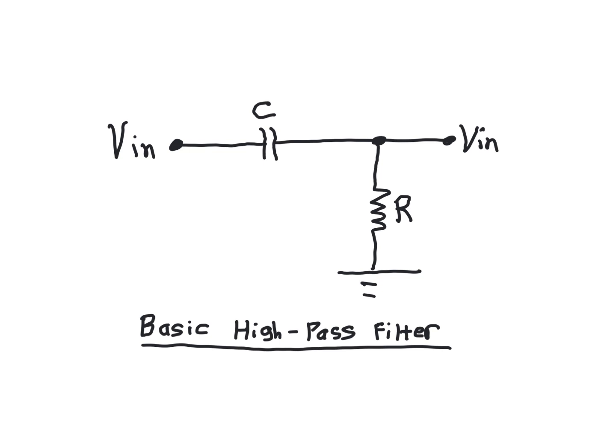Okay, again, this is the basic filter, and that should be the output of the filter. Notice that the position of the capacitor and the resistor are interchanged. Again, the operation is really just contingent upon understanding how the reactance XC changes with the frequency.